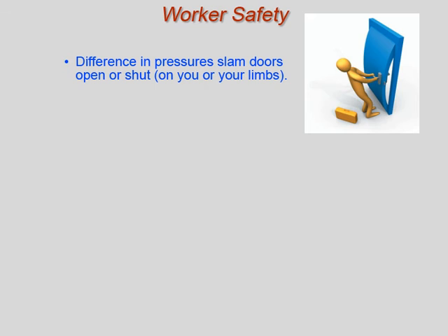Use caution around fan suction and discharge openings. Fan suction pressure will hold access doors and hatches closed or slam shut partially open doors, which could cause injury. Fan discharge pressure can blow access doors and hatches open with considerable force, which can cause injury.